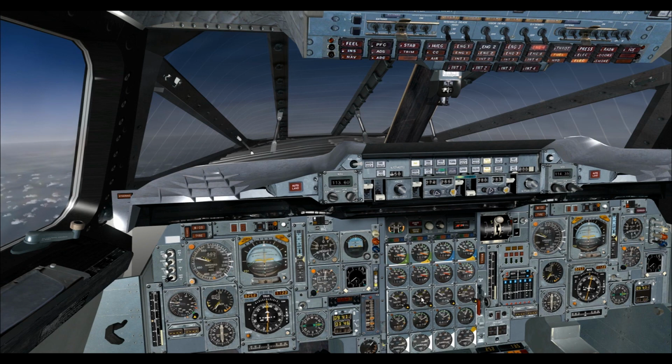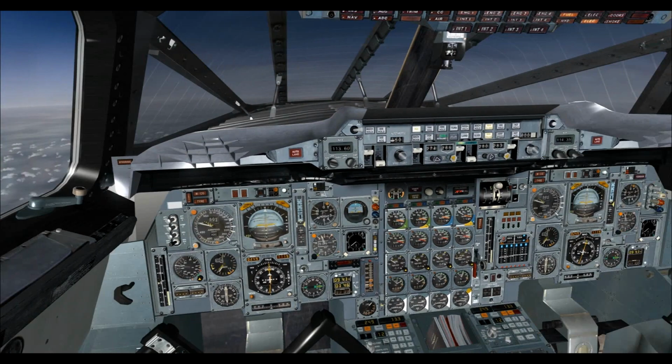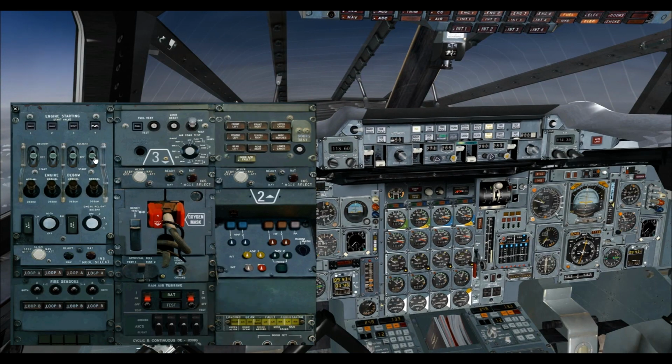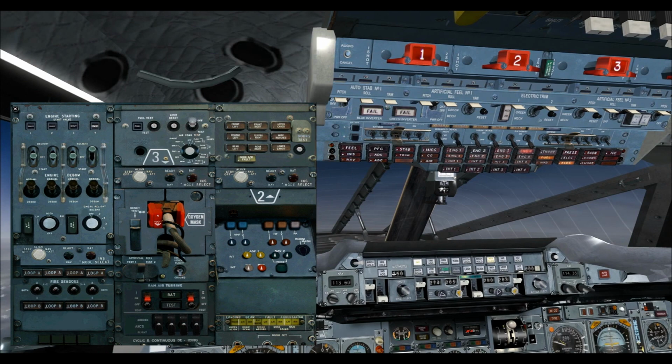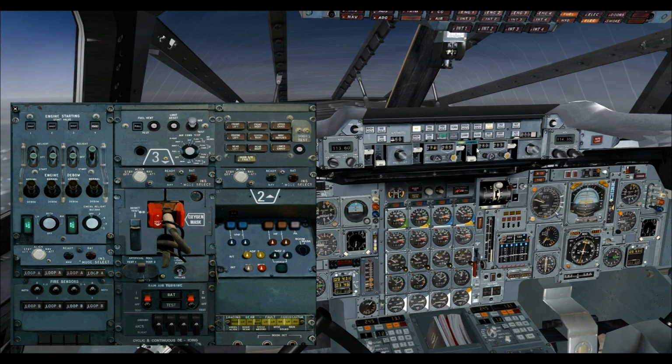It's going to lose altitude and speed, but you can comfortably fly on 3 engines. Okay, so after 20 seconds has gone by, you're now in a position to do the relight. So you're going to flip your relight switch to relight. You'll see that the start valve opens, and you can turn on your HP valve, and we should see the engine starting to light up.